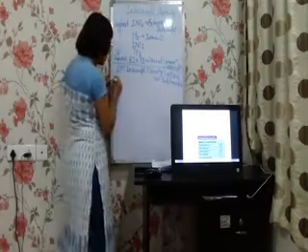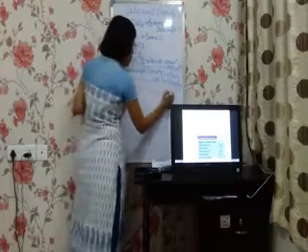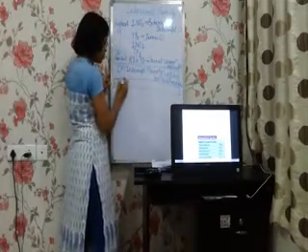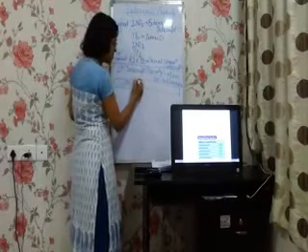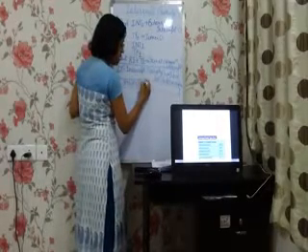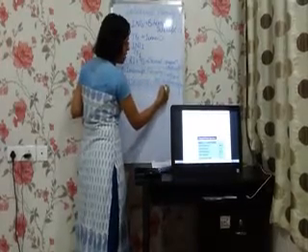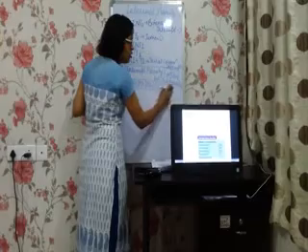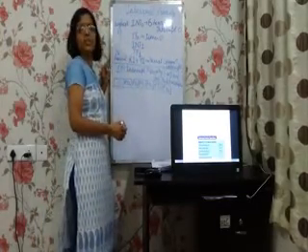This is the format of the IP register. Let us draw the format of the IP register. The first 2 bits are not there. Then PT2, PS, PT1, PX1, PT0 and PX0. Doesn't it look similar, students? Yes, the format is almost similar to the interrupt enable register.